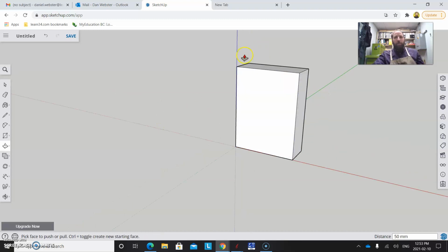Okay, so I'm not going to turn this into a component yet. I'm going to do a little bit more work. What I'm going to do is offset that by 20 millimeters. I clicked too hard. I want to offset that by 20 millimeters. It's letting me do it this time. So that's basically the thickness that I'm going to deal with. I'm making the carcass. I will be showing you the shelves here.